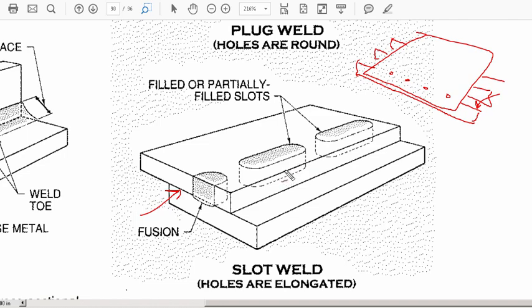We're going to penetrate the top layer of material, the top base metal, until we make contact with the lower base metal. So, part A to part B, we're going to burn through part A until we get to part B. Now, don't get me wrong, sometimes this can be facilitated by pre-done holes that make it a lot easier, but it's not always the case that those holes are going to be provided. Sometimes burn through is how they'll actually make the connection.